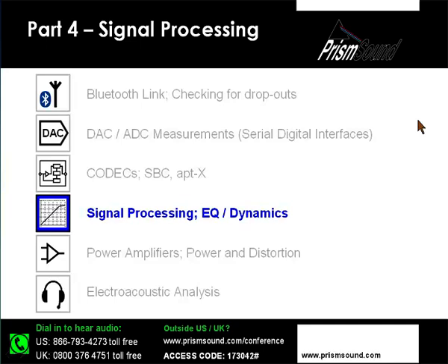Okay, thank you very much, Howard. And that's quite a compelling demonstration there, showing you two codecs running on identical hardware. In fact, it is the same board that Howard was running those two different codecs on, and it shows you that using the same Bluetooth link, consuming the same bandwidth, there is potentially quite a wide variation in the performance of the various codecs that you could be running on your Bluetooth system. So it's well worth understanding how you go about quantifying those differences in order to help you select the most appropriate codec for the device that you're designing. And in particular there we saw that the aptX implementation is particularly high quality when compared to the mandated subband codec.